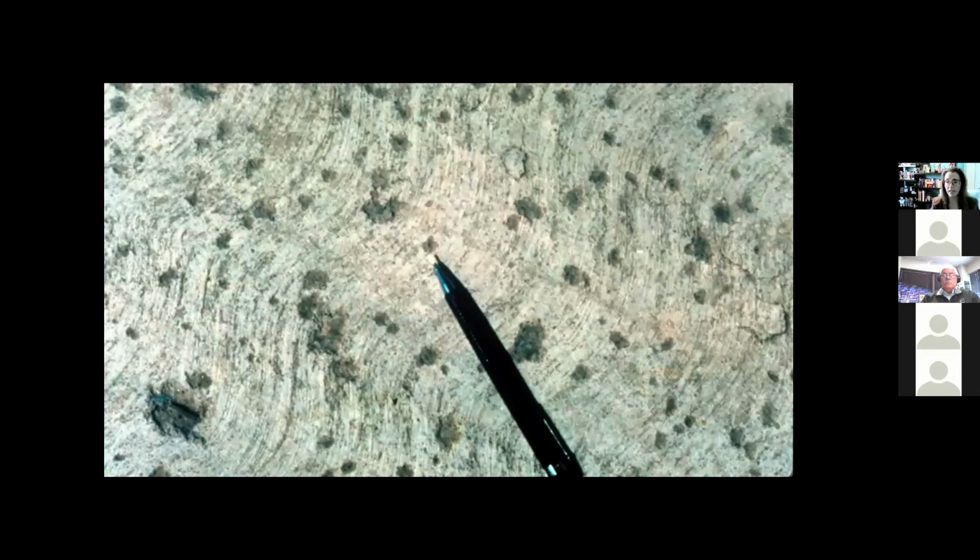There are pop-outs in fine aggregate that can form due to that ASR topic we talked about. So this is rupturing of the fine particles of aggregate on the surface. This issue is a durability issue because it's showing a chemical reaction occurring interior of concrete, and it may or may not need some sort of relief joint. It might need a sealer. It depends on what the surface is.